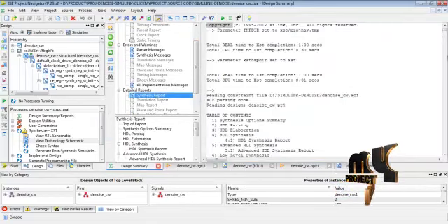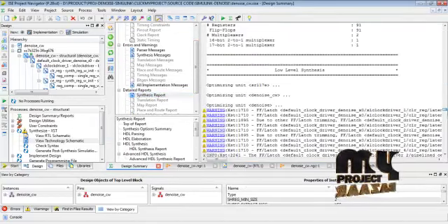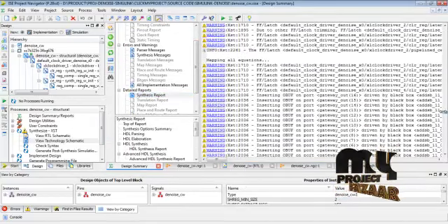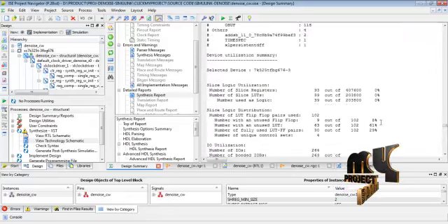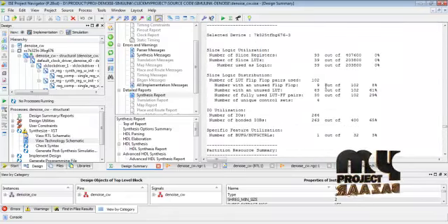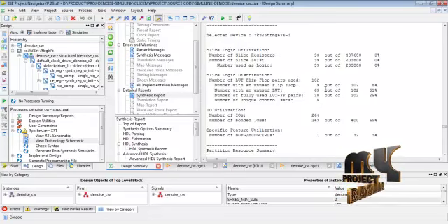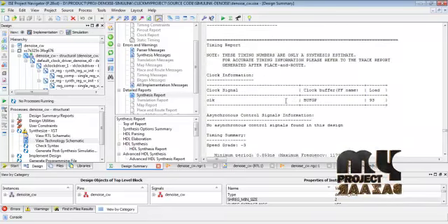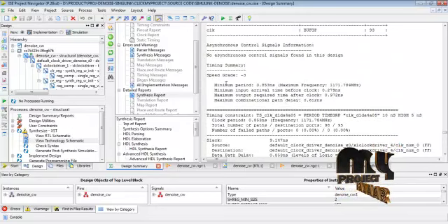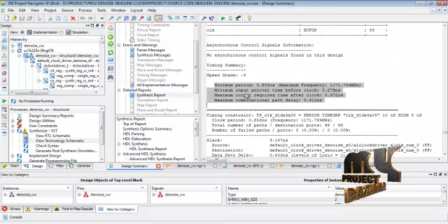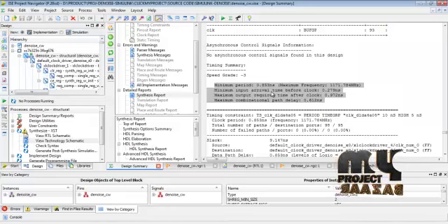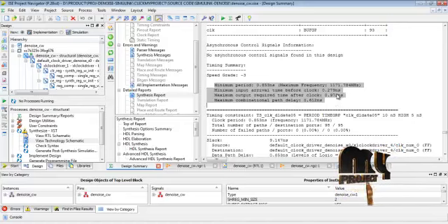This design summary shows the synthesis report for the overall architecture. This is our device utilization for lookup tables and slice registers. Then the flip-flop pairs used for the overall architecture. These are the bonded input output functions for the overall architecture design. This is the timing summary for the overall processing architecture. This is the minimum period and maximum frequency for the overall architecture. This is the path delay. This is the latency time for the overall architecture process.